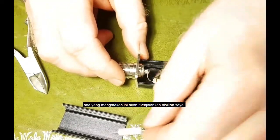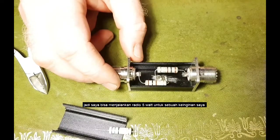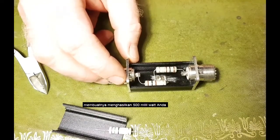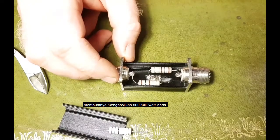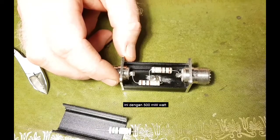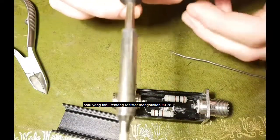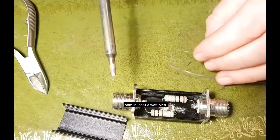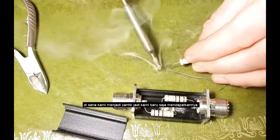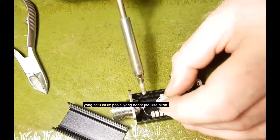Now the plan is that this will run my Whisper, so I could run a 5 watt radio. 10 dB would make it produce 500 milliwatts. I'm planning to run the FT817 through this with 500 milliwatts, which will give me an output of 50 milliwatts. One end is tinned on the resistor, this particular one is 75 ohm. 3 watt, by the way, a 3 watt resistor. There we go, beautiful. So we'll just get this one into position.